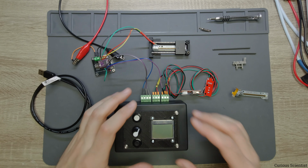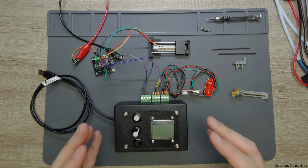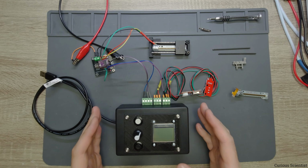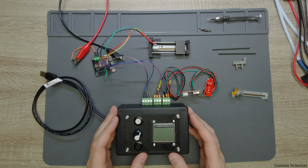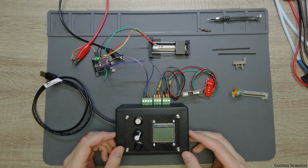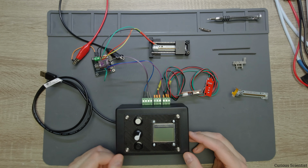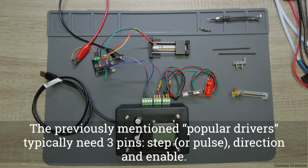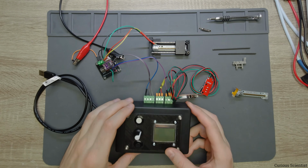So coming back to the control box, this is a very universal control box, because you can use it with any kind of popular stepper motor driver, because they work with the same principle. You just need to provide them the direction and the step signal. Sometimes they need an enable signal as well, but that is also here.